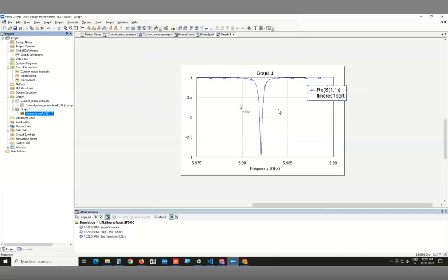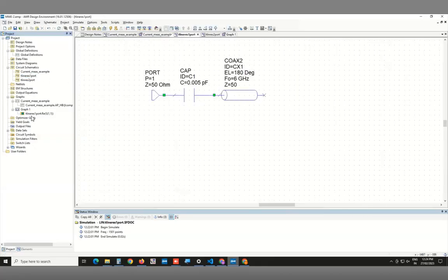So this is what you had to do in the first step, and part of this is just exploring: does your graph make sense? What is the correct frequency range? You've been told it's a resonator, so it's going to have some frequency response. And I think many of you didn't even get to this point, because maybe you were just looking at the magnitude, saw nothing, and basically that was the end of it. Okay, so that's now the reflection coefficient of the resonator in schematic 1, which is the 1-port resonator, right?